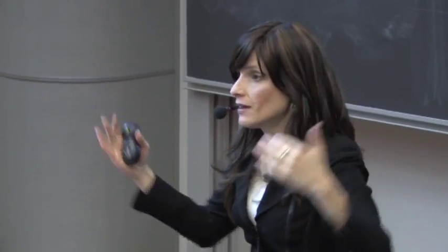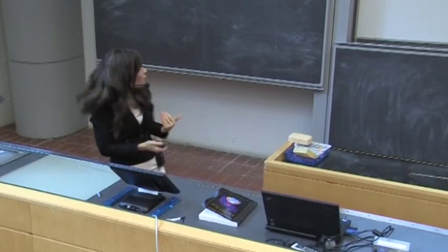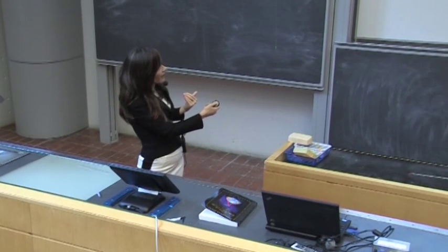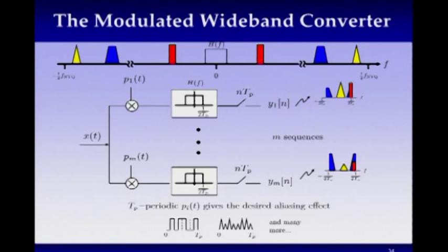Because convolving with a delta train means you take your signal, then you shift it to the right, you shift it again, shift it to the left, shift it again, and sum everything up. Well, that's the definition of aliasing. So what you're going to get at the output is something that looks like this. Now, in fact, you'll get this all over the spectrum. So basically, you're aliasing all of this data all over the spectrum.